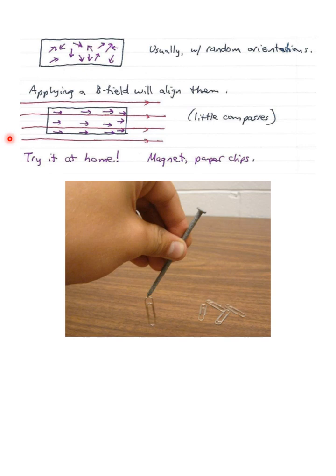When we think about what we call permanent magnets, like a refrigerator magnet, these are materials that have been brought up to a high temperature. It's called the Curie temperature. It's almost like melting it. You're not turning it into a liquid, but I think of it as melting the domains. You're making the domains very flexible. So you bring it up to a high temperature. For iron, I think it's something like about 1,000 degrees Celsius. And you subject it to a magnetic field, as you can see in my picture in the middle here, and those domains will align. Then you bring it down to a lower temperature, and they will be frozen there.